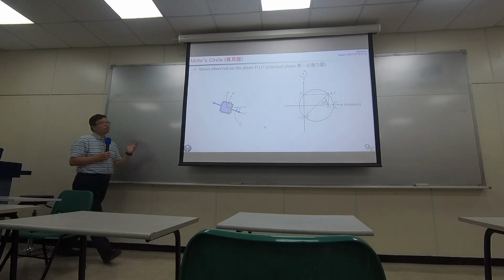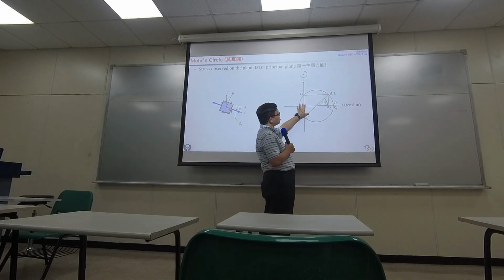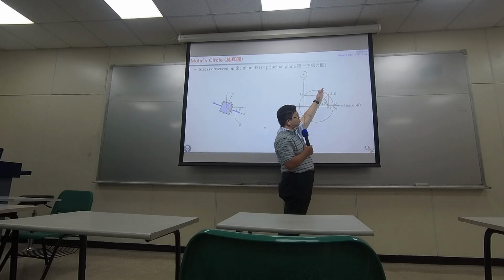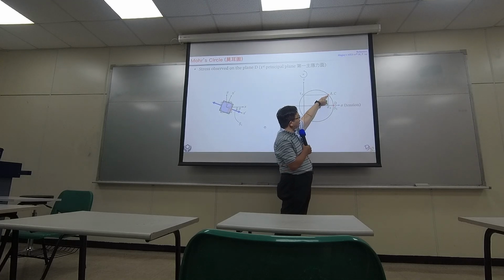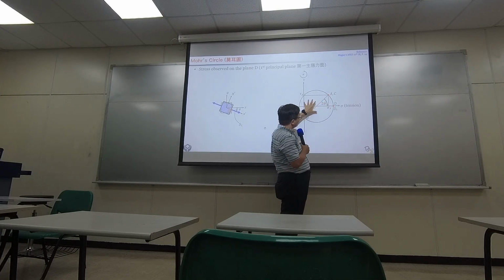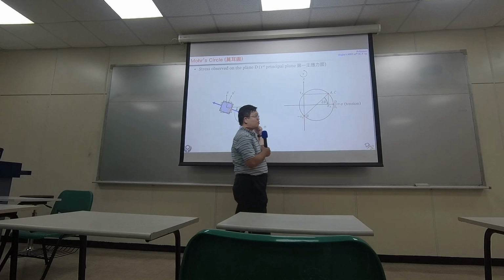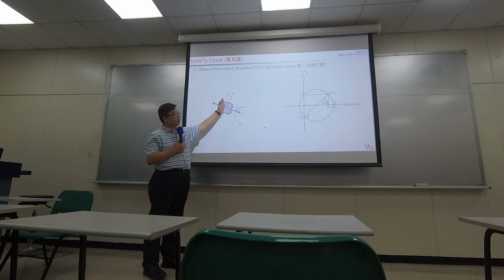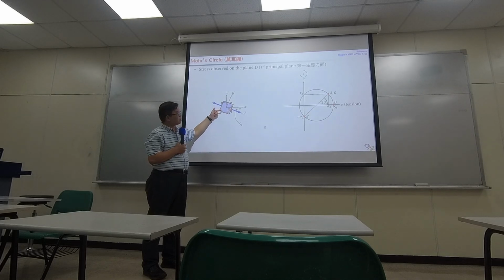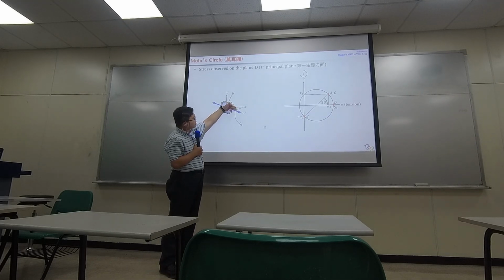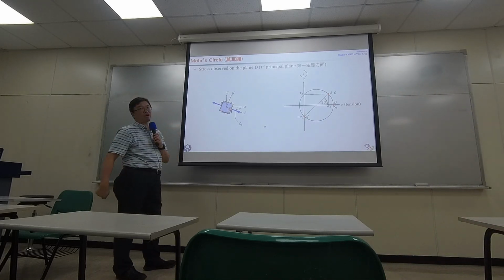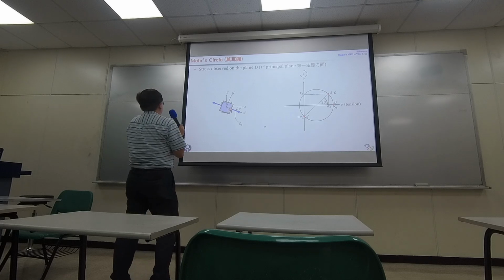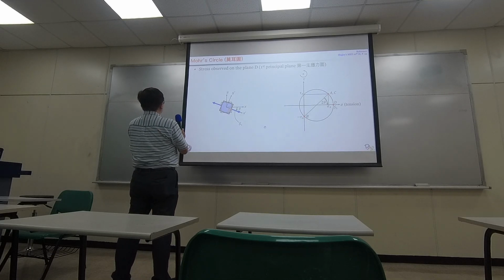So if you now focus on the Mohr circle and try to change the observation angle by 2 theta degrees, you move from this point A to a point D. So over here, you change the angle by 2 theta. In the real world, you will be changing the observation angle by theta. So if you change the coordinate by theta, like making a clockwise rotation by theta, you move on to a new coordinate, we call it x prime right here. So earlier you are observing the element straight.